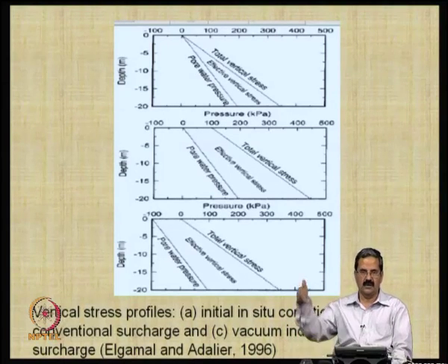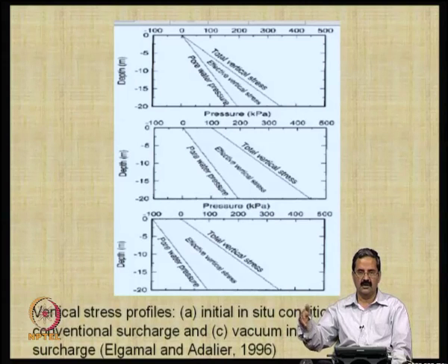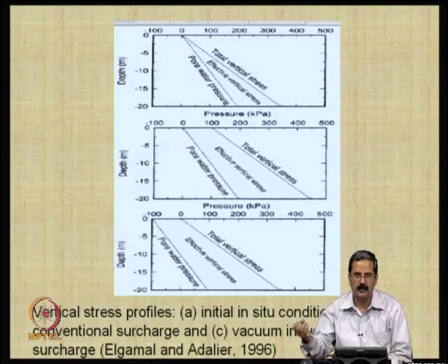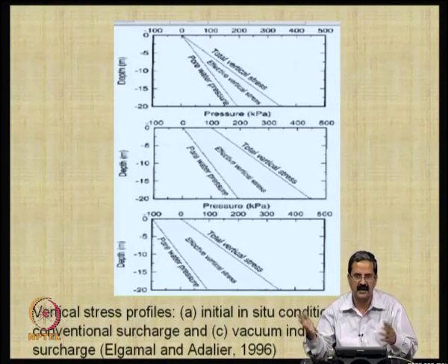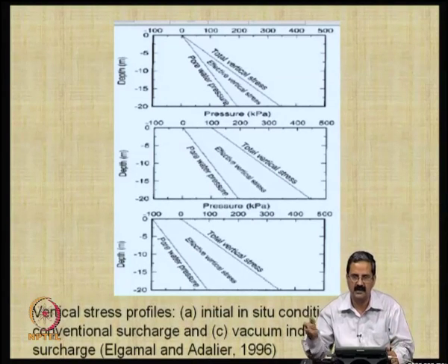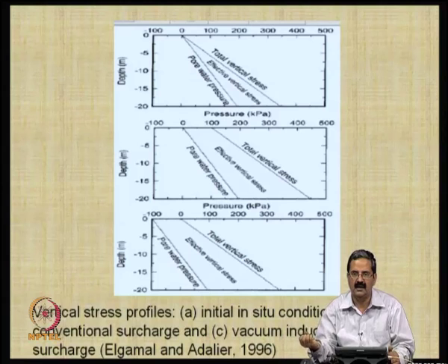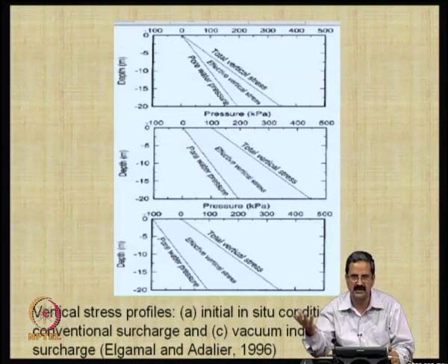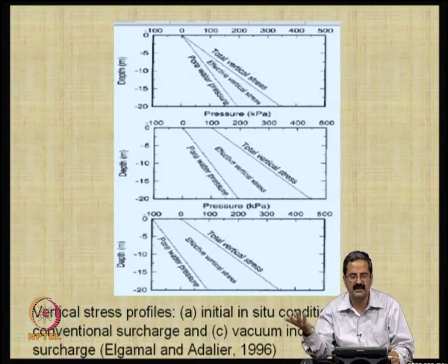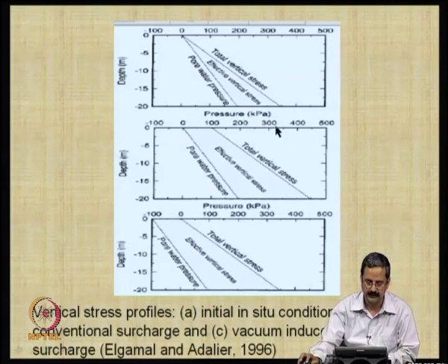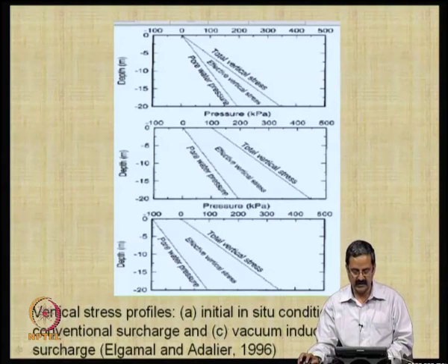If there is a water pressure rising, water pressure is nothing but the pore pressure, the excess pore pressure. If you put a standpipe next to the soil in an undrained situation, there is always an excess pore pressure in relation to the atmosphere. You just measure that in terms of the column of water, like if it rises by 3 meters or 2 meters, into gamma, meaning 10 kilonewton per meter cube, that is approximately the pore pressure. So, this is the in situ condition.